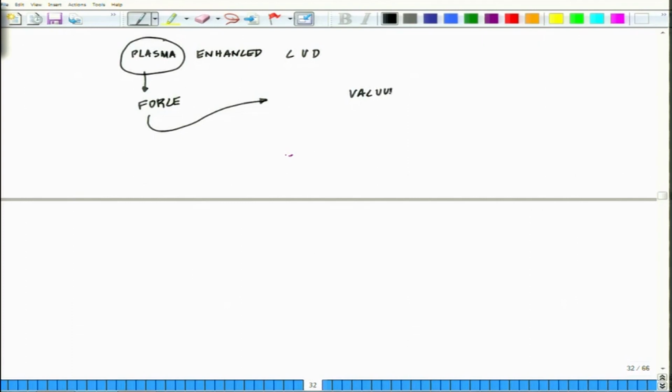So these are those requirements. A vacuum unit you will be needing, then you will be needing a very high power supply, you need a gaseous precursor. In other words, you need a decently high power supply, and you need pretty specialized apparatus to have this plasma enhanced chemical vapor deposition take place.